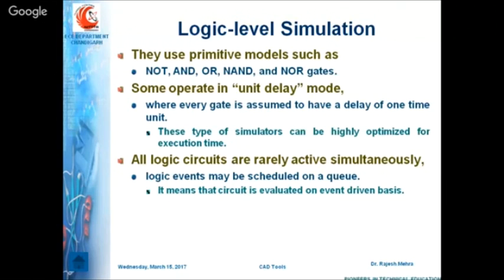Then logic level simulation. As I told you, you have different options. You can capture your design in the form of gates, or in the form of transistors. Here you can see that different gates may be there in your design: NOT gate, AND gate, OR gate, NAND, NOR. A number of gates may be there, and each and every gate is related with some unit delay. For example, an inverter has unit delay of 1, and NAND and NOR gates have unit delay of 2. So you can count the number of NOT, NAND and NOR gates in your design, and based on that number you can calculate the unit time delay of your design. These types of simulators are fast, but they are not accurate. They can give you just an estimated idea about the delay of your design, but they can't give you the exact delay and exact rise time and fall time delay.